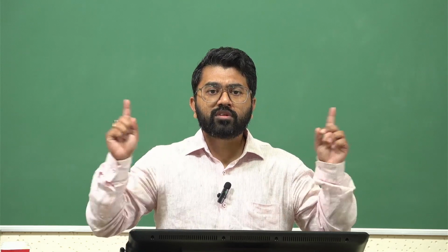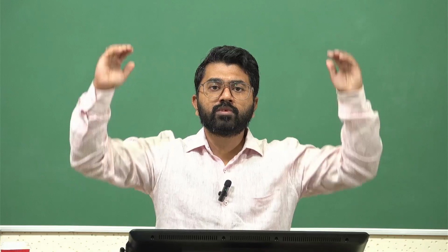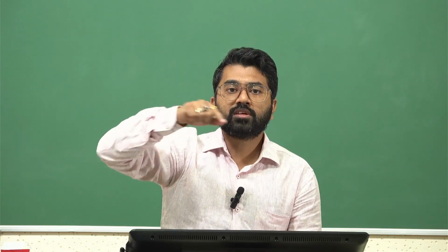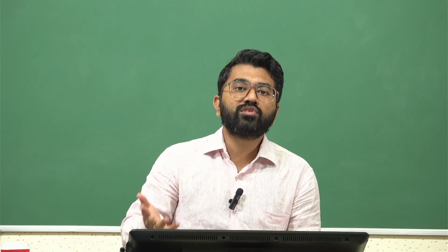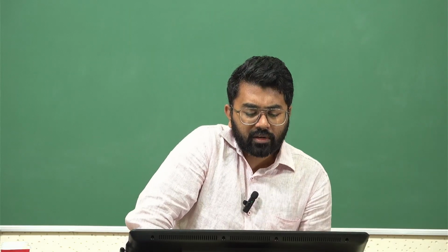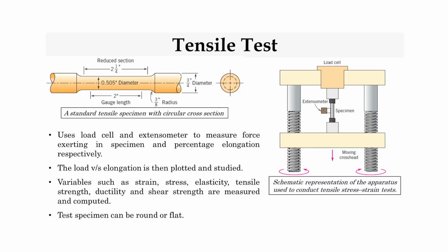So you have a moving cross section with certain screws which takes the platform up and down and causes the displacement, and the load cell keeps on measuring the loads, and finally what you get is load versus displacement data, or load versus elongation data. This is plotted and studied. Variables such as strain, stress, elasticity, tensile strength, ductility, and shear strength are measured and computed. So many different quantities can all be computed from just the force versus displacement data, dynamic data, which has been converted to stress and strain, right?